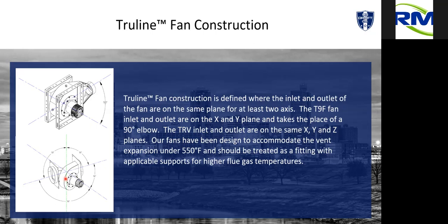One of them as far as 165 feet in horizontal plus fittings. And the problem with that is that the manufacturer only allowed for 100 feet. So obviously they couldn't fire those. So we actually shipped them 6 of the inline fans and 4 of the 90-degree fans.